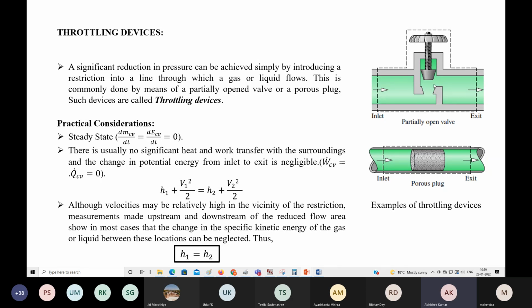Since this is a narrow passage over here, pressure drop is happening. Here high pressure, here low pressure. Because of that, velocity here is increasing. In the case of this porous plug, maybe velocity gradients are there over here. After going a little downstream, that velocity also comes back to normal. That's what even enthalpy variations are. So this equation we have considered like this.